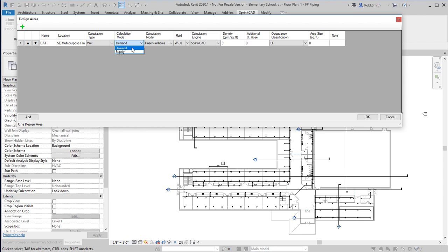The program will then calculate back to the source point and tell you what is the required pressure and the required flow to meet that demand at that most remote point, taking in all of the other flowing outlets and how much they flow based on their actual pressure in that minimum pressure flow condition.